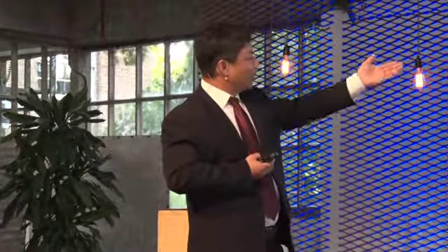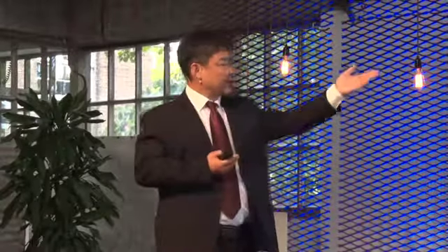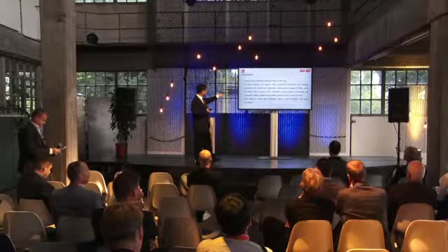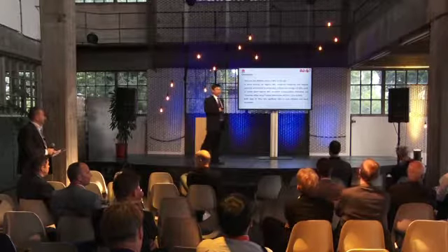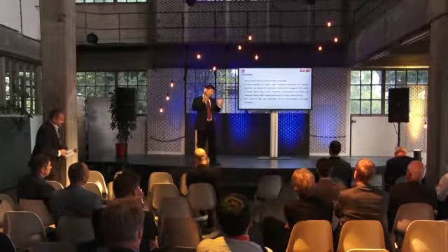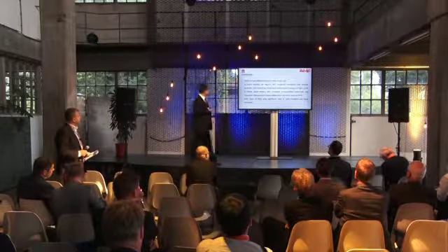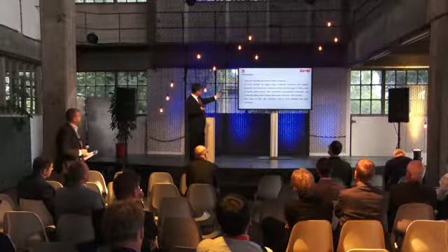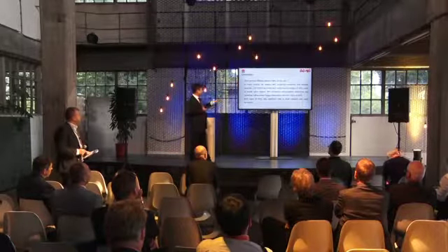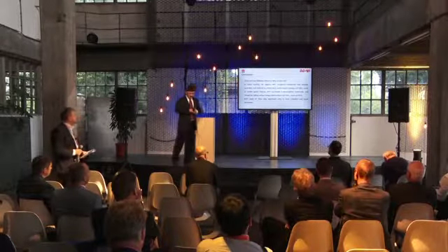For the steady traffic region, the white etching layer has nanocrystalline martensite caused by rolling contact fatigue. But it's not a very typical squat. It's generated by the white etching layer. Both white etching layers play roles in crack initiation and squat formation.